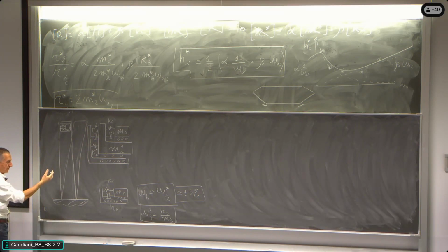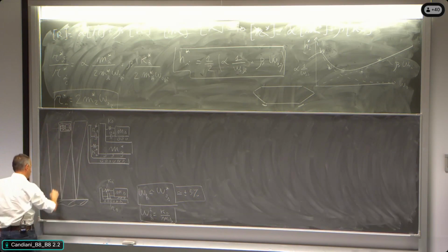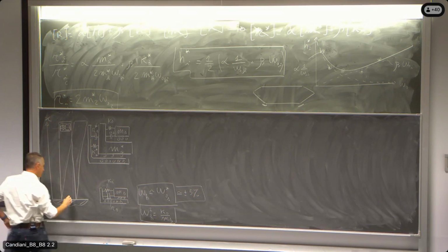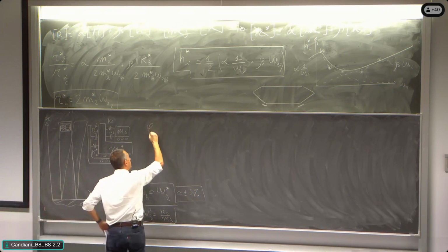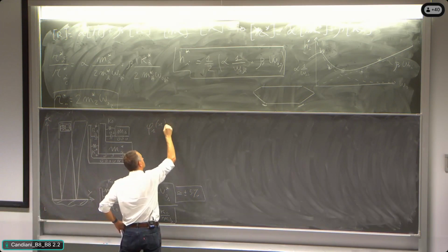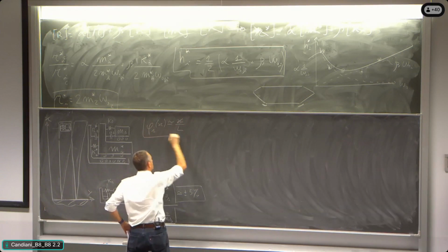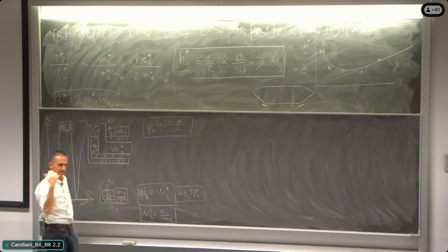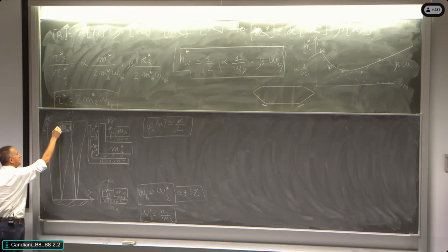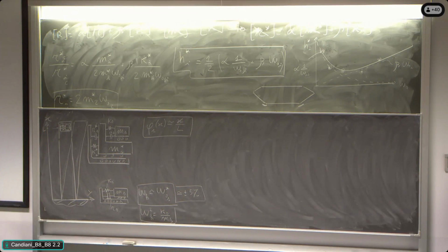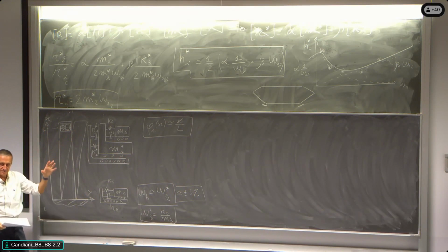And making reference to a mode like that, let's say we are making reference to a representation where this is x, this is y, and we are representing the mode with phi 1 of x equal to x divided by L. With this choice, we are saying that at the location L, the deformed shape is normalized to 1, all right?